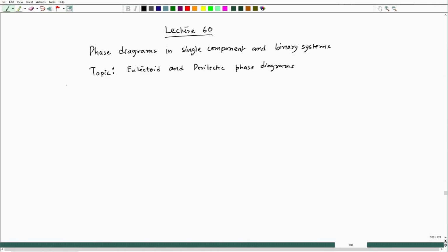Now, continuing our eutectoid phase diagram, we are considering a binary solution with A and B, these are the two metals, and we are taking X A and X B, these are the two mole fractions of A and B, and when we add them together we are getting 1 mole of solution, right. Of course, we are taking temperature and pressure constant, and then we are trying to see the free energy composition diagram and see what is the stability of different phases.